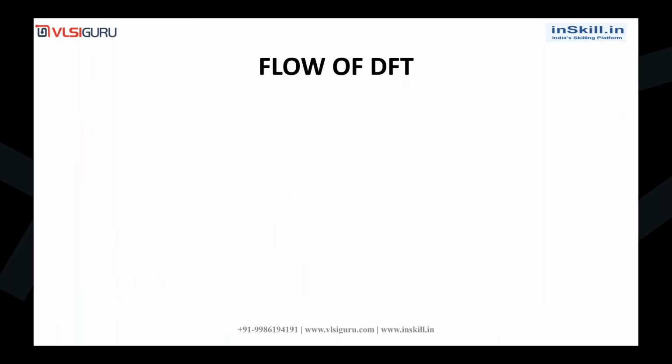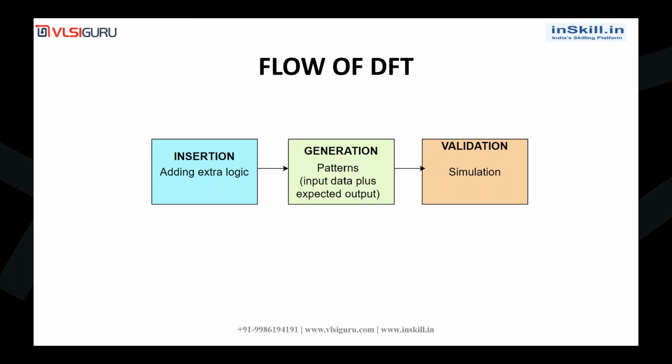Now we'll try to understand the flow of DFT. First we have the insertion phase. In insertion, we will be adding extra logic into our design, like scan insertion, MBIST insertion, boundary scan insertion. So we will be adding our own test structures into the design.